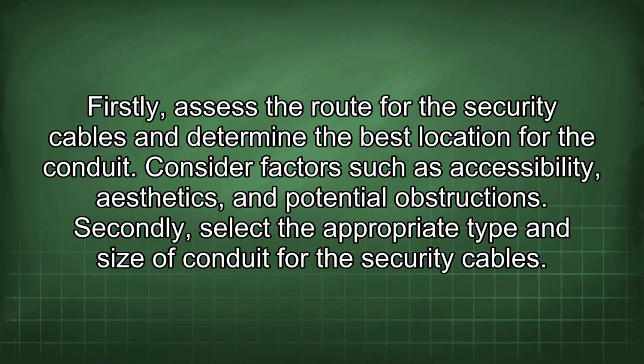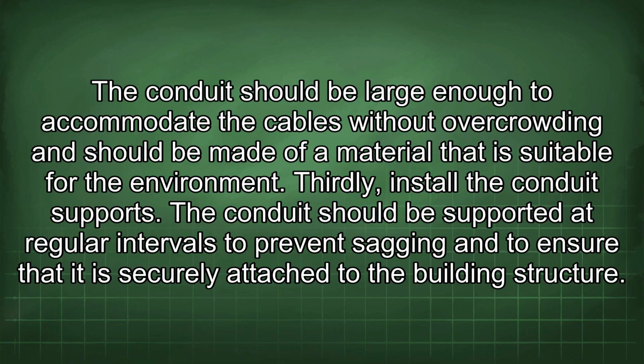Firstly, assess the route for the security cables and determine the best location for the conduit. Consider factors such as accessibility, aesthetics, and potential obstructions. Secondly, select the appropriate type and size of conduit for the security cables. The conduit should be large enough to accommodate the cables without overcrowding and should be made of a material that is suitable for the environment.